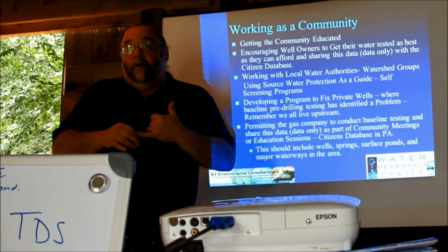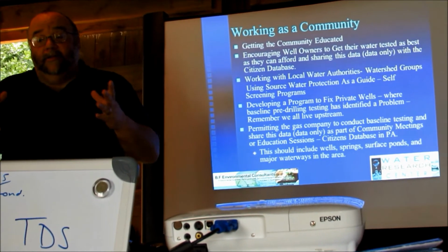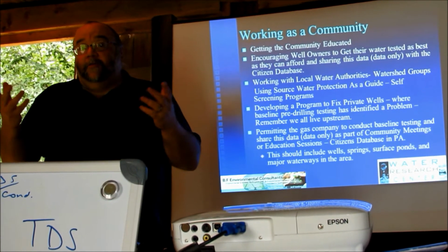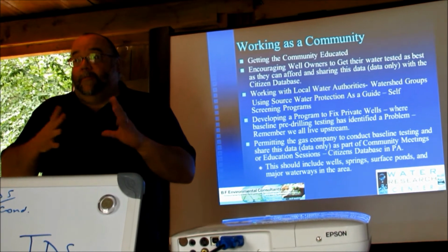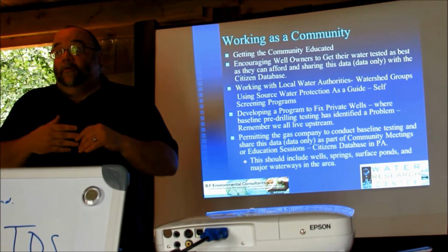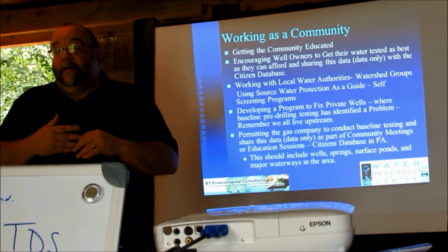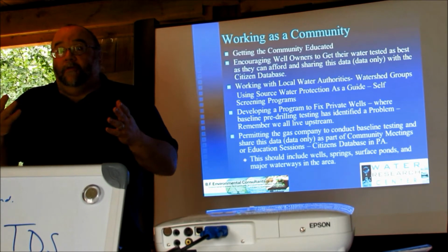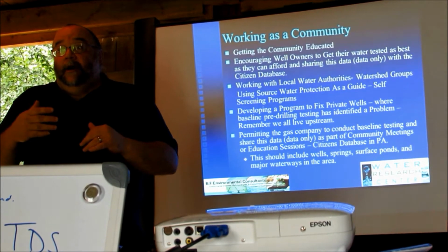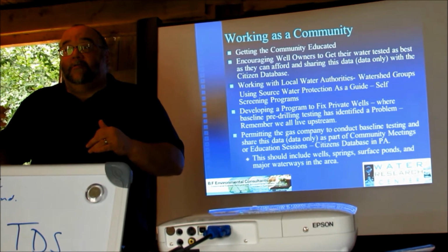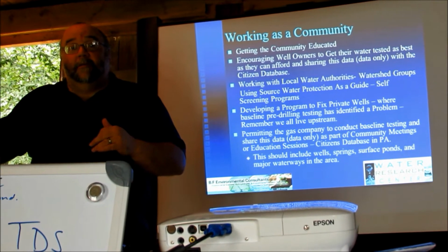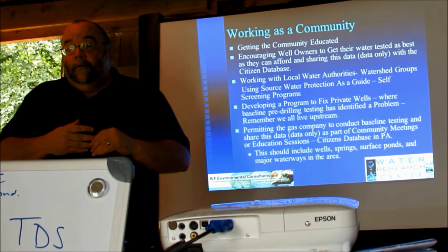Well, iron could be treated with water softeners. Iron could be treated with oxidizing filters and filtered out as particles. There's a couple different technologies. Ozone will work for iron, ozone will work for manganese, water softeners work for iron and manganese. If that doesn't work for arsenic, there's actually activated material that scavenges the arsenic out.